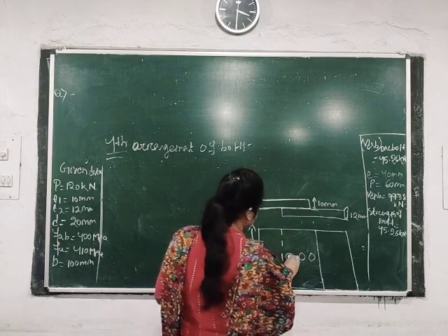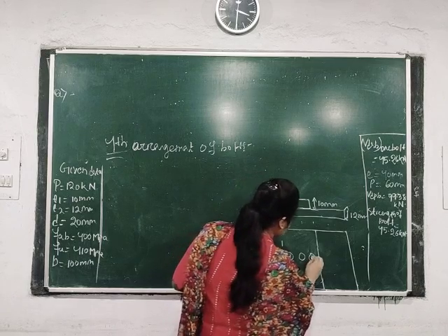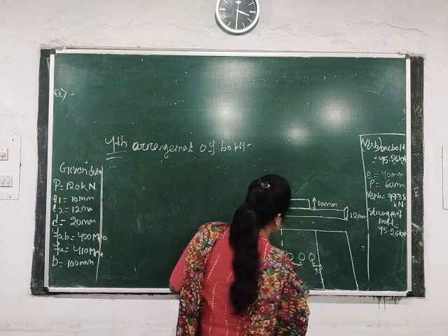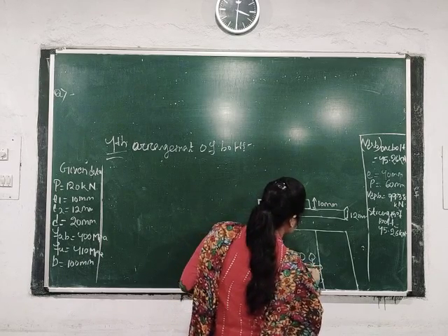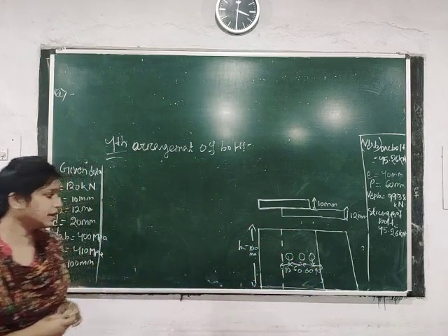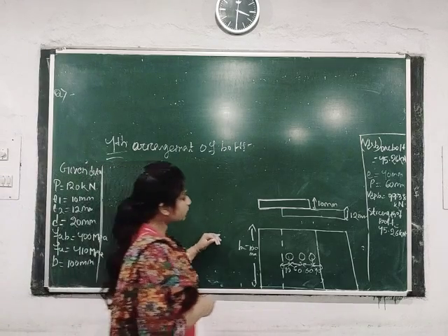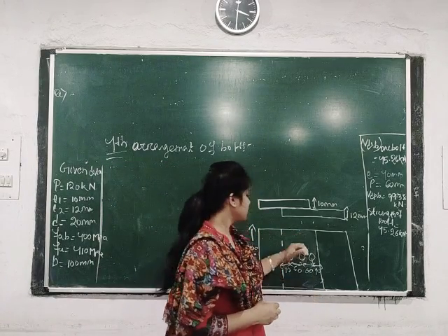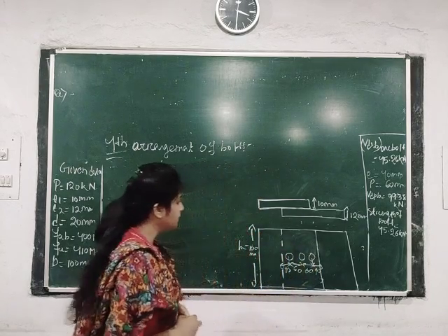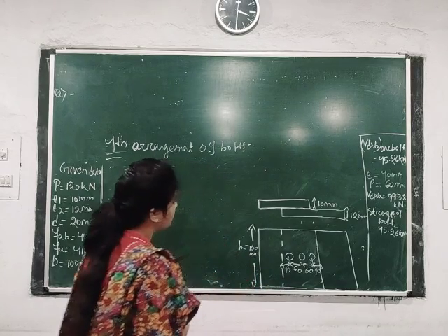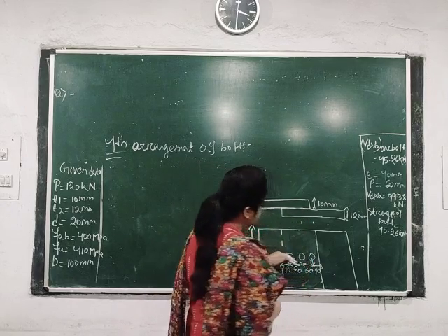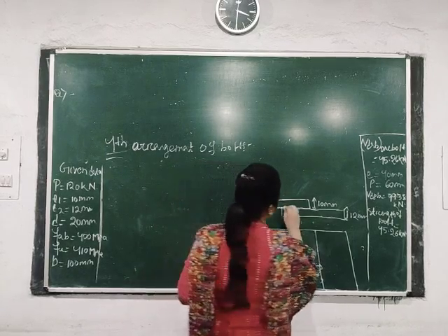Okay, so take the end distance as 40 mm, here also the end distance as 40 mm, and the pitch distance as 60 mm, and here also the pitch distance is 60 mm. As our width is restricted to 100 mm, we can provide 3 bolts in one row. So you can provide the bolts this way. Here in the elevation these 3 bolts will be seen.